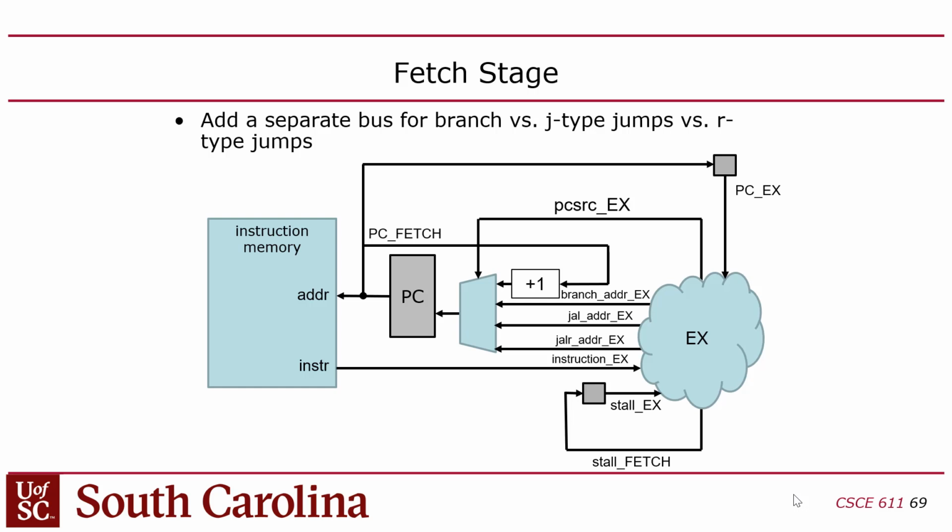And it converts it to a stall, and then it sees, oh, it's a stall, I don't need to stall. And you end up with this infinite loop happening within the clock cycle. It's not clocked, it's a combinational loop. So ModelSim will lock up if that happens, because it'll trigger a cascade of circular events where something happens that triggers an event, which triggers something that triggers another event, and that happens endlessly.